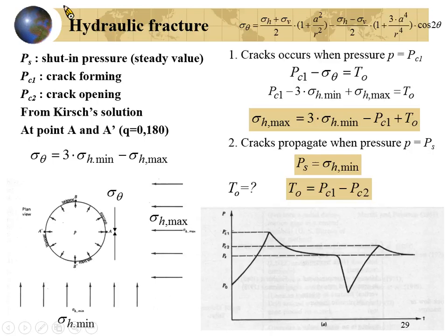If I am lowering down the borehole camera and I found a fracture like this, but not vertical. This will be vertical, right? So it will appear two times around a hole, here and here.